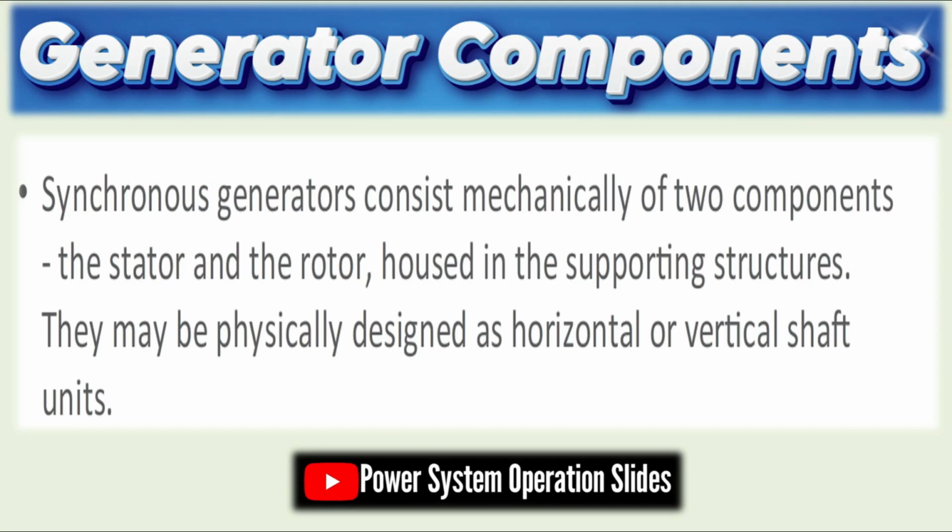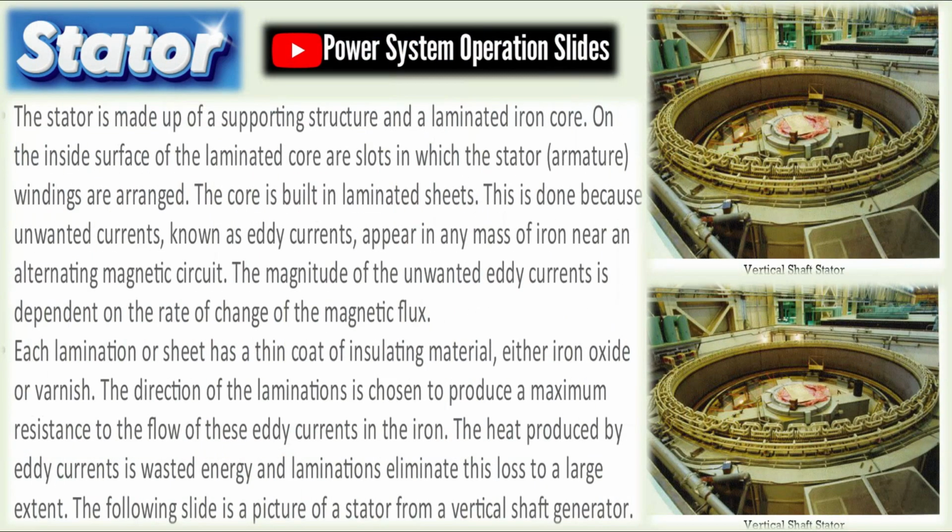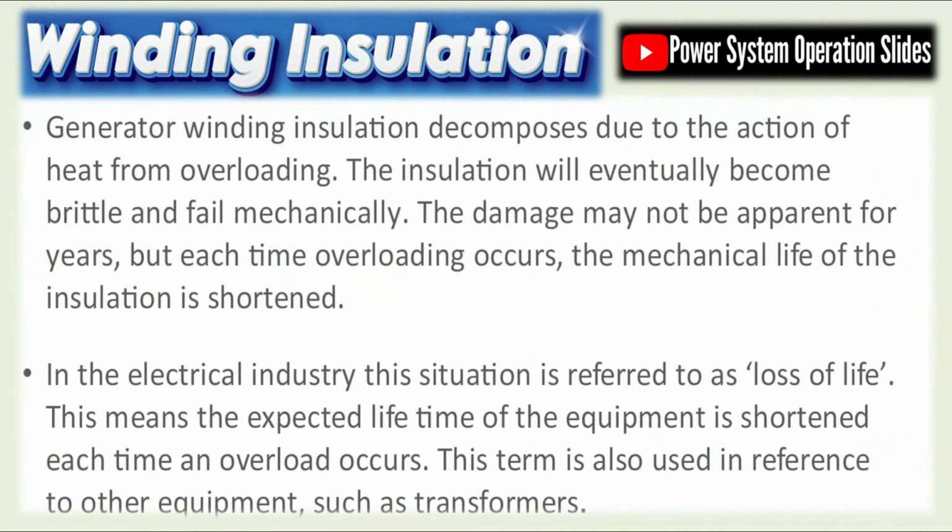Nuclear plants require strict safety systems, redundant cooling, containment buildings, emergency shutdown systems (SCRAM), and monitoring systems. Spent fuel is stored in cooling pools and then transferred to dry casks or reprocessed. Despite high initial investment and social concerns, nuclear plants offer stable, low-emission, high-capacity electricity ideal for long-term energy security.